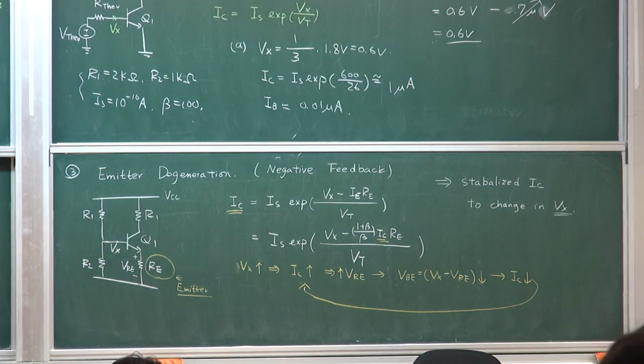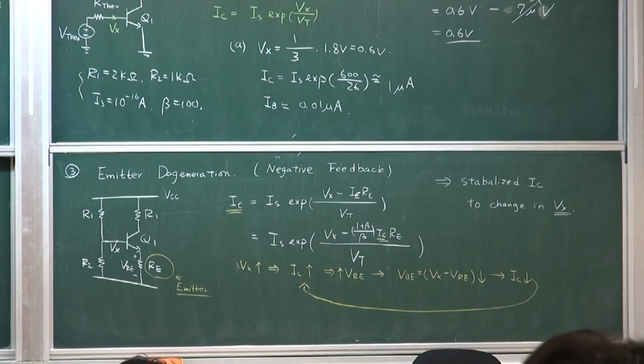This is called a single stage biasing or self-biasing, meaning that I don't need an additional branch. In the previous types of circuits, we actually add an additional branch for the biasing. Here I simply have one branch of current that splits right here to provide base current to allow the circuit to function in active mode. And then it self-biases itself.